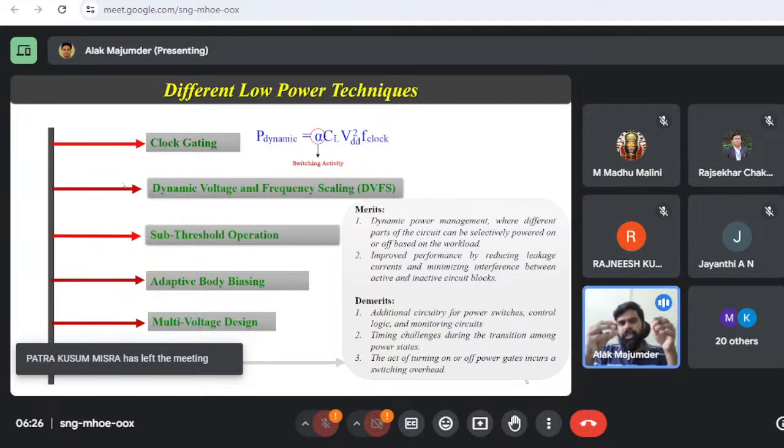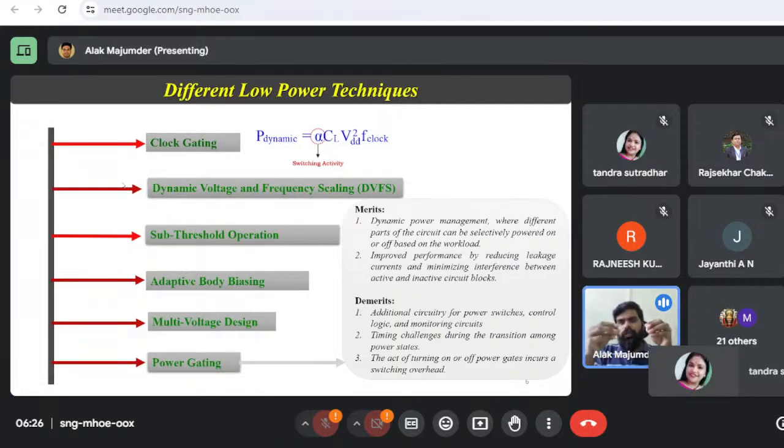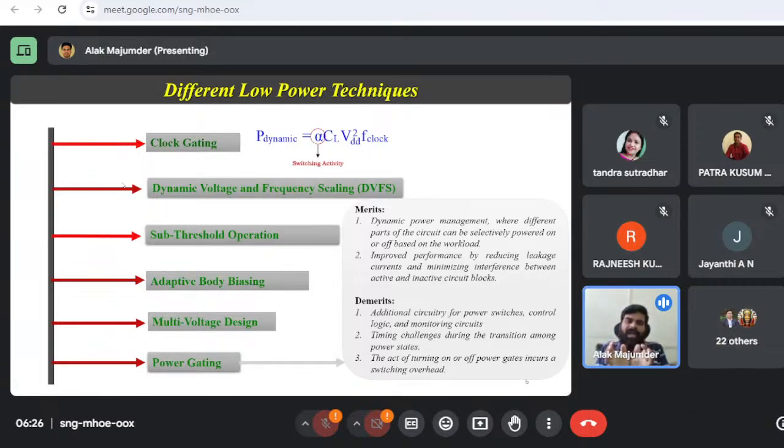Because that switch should be able to draw a large current which is drawn by your logical core. For example, you had a circuit which draws a current of 10 milliampere, right? Because in between the power supply and the logical core I have connected another third party, that third party also should be eligible to draw 10 milliampere of current, right?